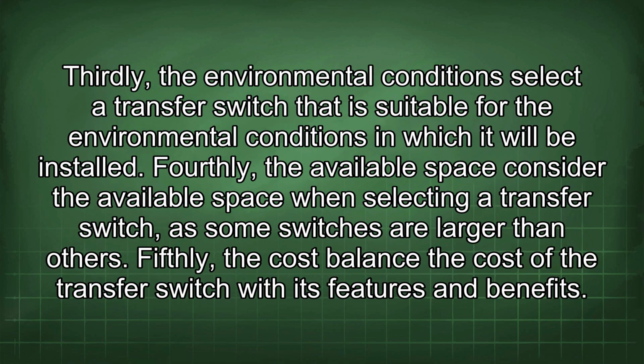load. Thirdly, the environmental conditions. Select a transfer switch that is suitable for the environmental conditions in which it will be installed. Fourthly, the available space. Consider the available space when selecting a transfer switch, as some switches are larger than others. Fifthly, the cost. Balance the cost of the transfer switch with its features and benefits.